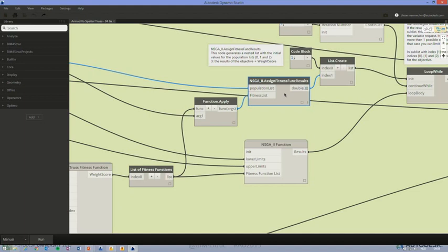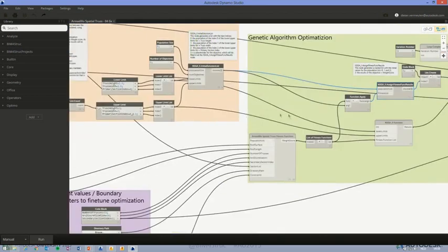Making some constant values, so there are things that are not design variables, which are just the constant values. It needs to know how many trusses you are using along the length of that roof, so that it can identify the longest truss, of course. It needs to know the arc discretization,